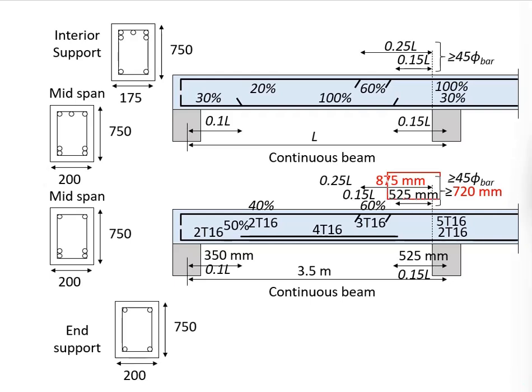If you round up the distance for the top reinforcement bar here, it will give you more reinforcement. That means the top reinforcement bar, you have to round it up. Now, if you round it down, the reinforcement bar will give you more area. Then the bottom bar here, this distance will have to be rounded down. That is the basic principle.